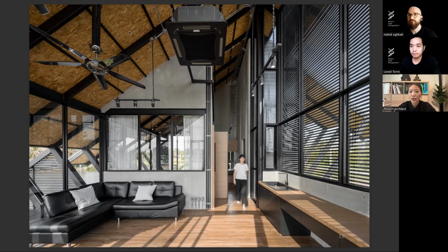That's a wood, and you put on felt paper after that, then put on the asphalt shingle, with no need for screwing. It is the best option for water draining, so there will not be any leakage on the roof.